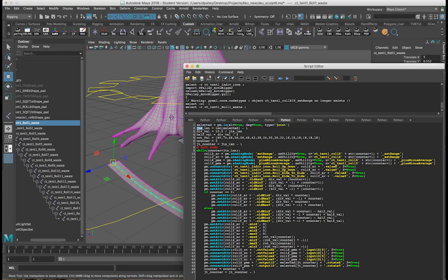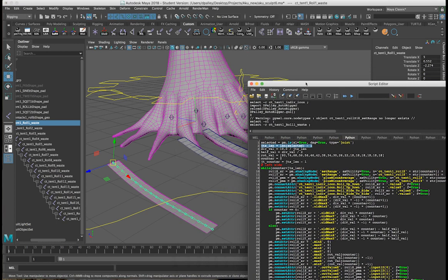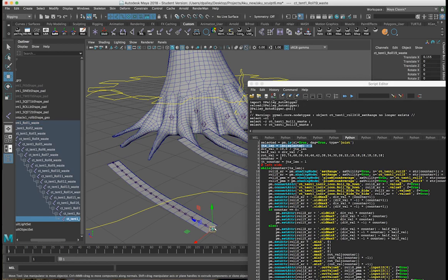This gets us the number of joints in the system, and it subtracts 1 based on the waist joint here. If you don't have that waist joint in your system, you can just get rid of this -1. The div value here takes the max value of the attribute on the icon and divides it by the number, so that's going to give us that increment number I was talking about. So 0.55, somewhere around there. The half value, I'll explain what that's doing, but you can see it's essentially taking that increment value and dividing by 2, and I'll explain what that is in a little bit.